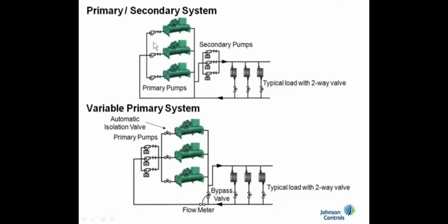What you'll notice is the difference: primary-secondary is, again, typically going to have dedicated pumps on the primary side, and secondary unheadered. But now we take these two sets of pumps and combine them into one set of pumps that are all headered together. Now this doesn't mean, just like primary-secondary, you couldn't dedicate these pumps. But if you do dedicate these pumps, then you can hurt some of the possibilities for control that can optimize energy savings.